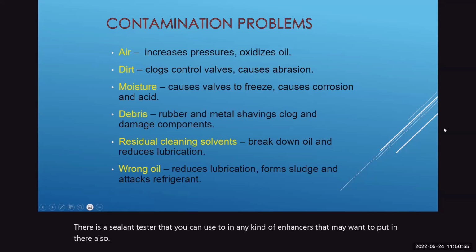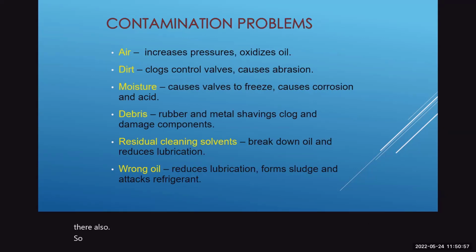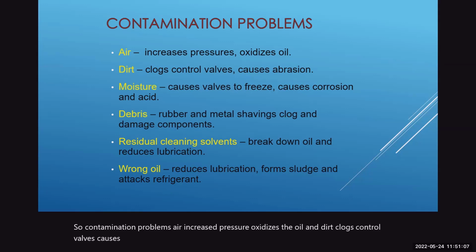So, contamination problems. Air and increased pressure oxidize the oil, and dirt clogs control valves and causes abrasions. Moisture causes valves to freeze, and then causes corrosion and acids.